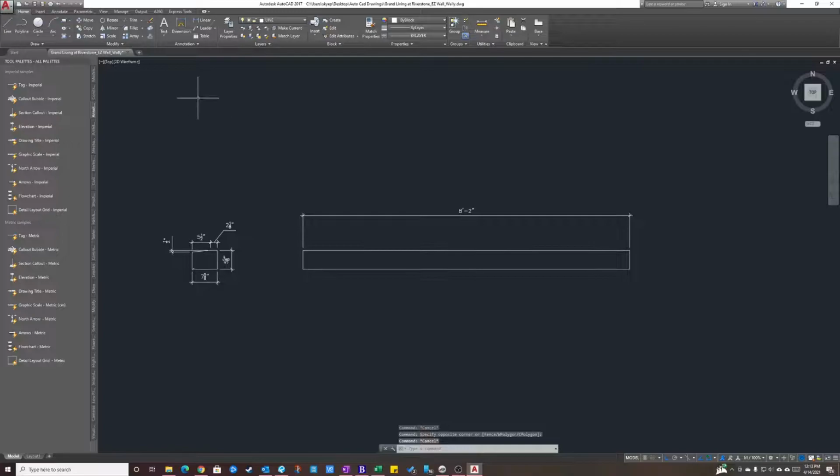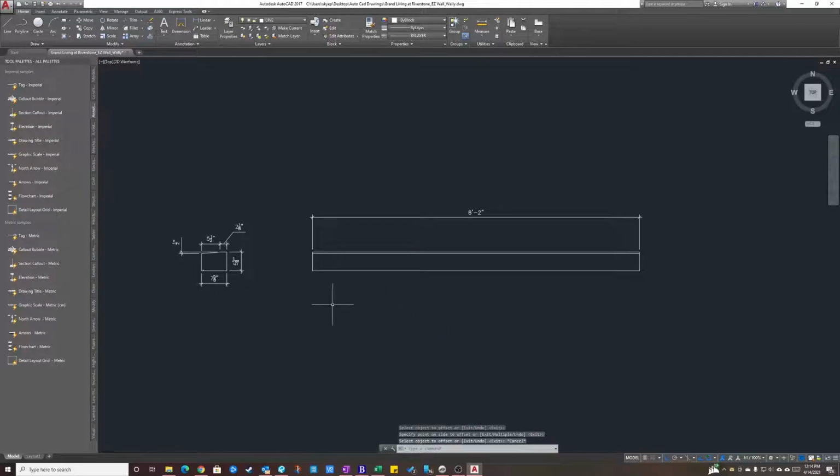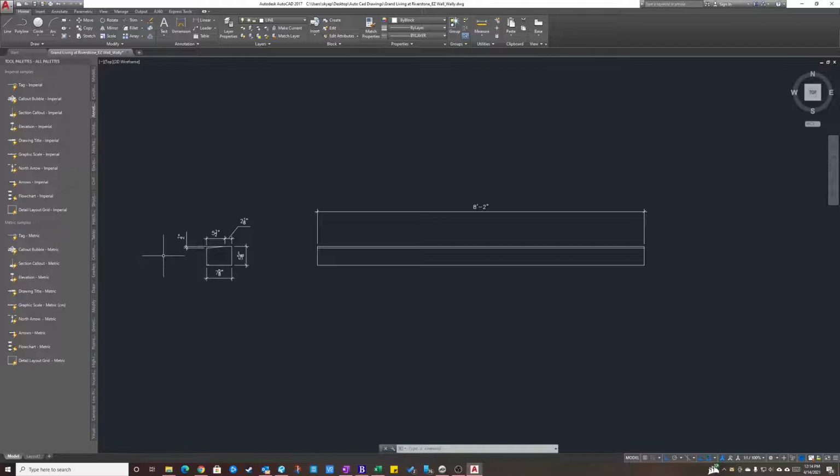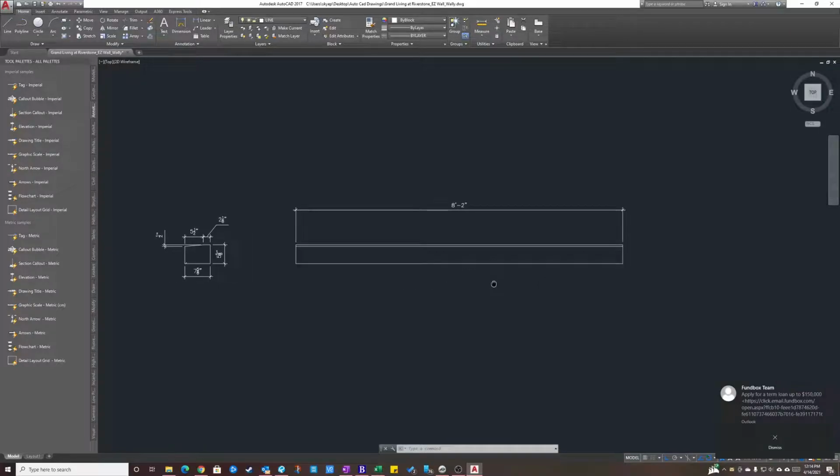See? All right. So we're going to use our offset tool again, and we're going to offset it by 1/2 inch, which is 0.5. Enter. Now you come over here, you click on the line you want to offset, and you drag it down in the direction that the offset is supposed to occur, which is down. You're going to left click. That's going to set that line. You can hit escape. So now what are we looking at? We are now looking at this stone the way it would appear if we were standing in front of it, looking at it straight forward.